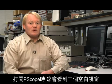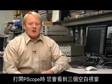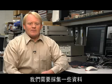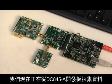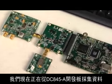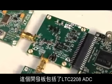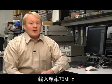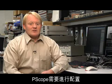When you open PScope, you will see 3 empty windows. Before we can look at the features of PScope, we'll need to collect some data. We are collecting data from the DC854D-A demo board, which includes the LTC2208 ADC. We are sampling at 100 megasamples per second, and we have an input frequency of 70 megahertz.